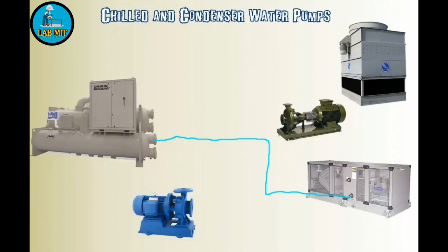Alright, so we've got the chilled water coming at the bottom of the coil. Now we want to draw the water coming back out of the coil that's ready to go back to the central plant and get cooled down again. So that'll be this darker color here. And we'll send it this direction. And I'm sorry, pipes don't normally go on a diagonal slant like that, I promise. But it comes into the inlet of the pump.